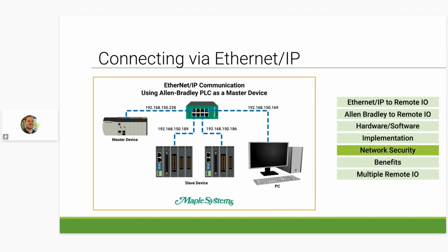Here on the left, you can see how the network topography will look for this application. As you can see, it is just about identical to the Modbus network topography. The benefits of using EtherNet/IP as a communication protocol are speed and bandwidth, which can run at high data transfer rates and handle larger amounts of data, ideal for applications requiring real-time control and monitoring.